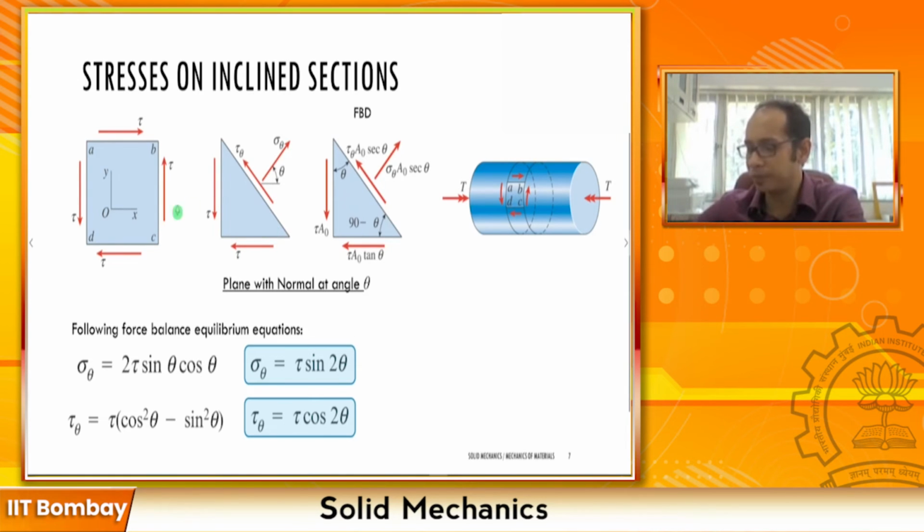So here what I have done is that we have cut this member over here, the entire section plane, to which the normal, so this is your normal vector, makes an angle of theta to the horizontal, exactly in a similar analogy to what we did for the pure axial case. Now once you have that, from the stresses you get the forces, remember this particular phase by A divided by cosine of theta and so on.